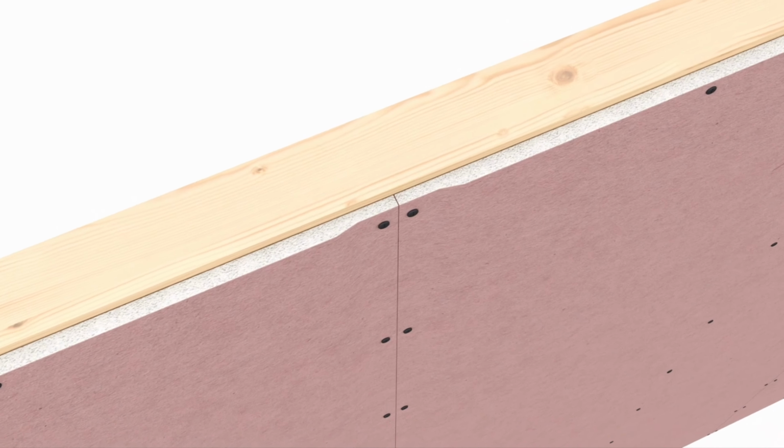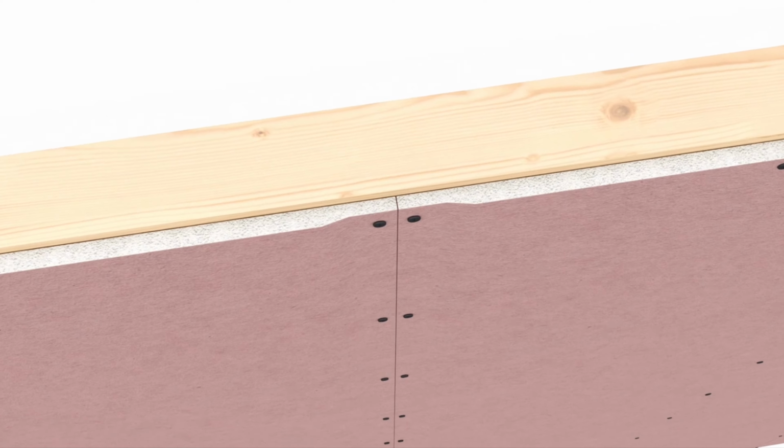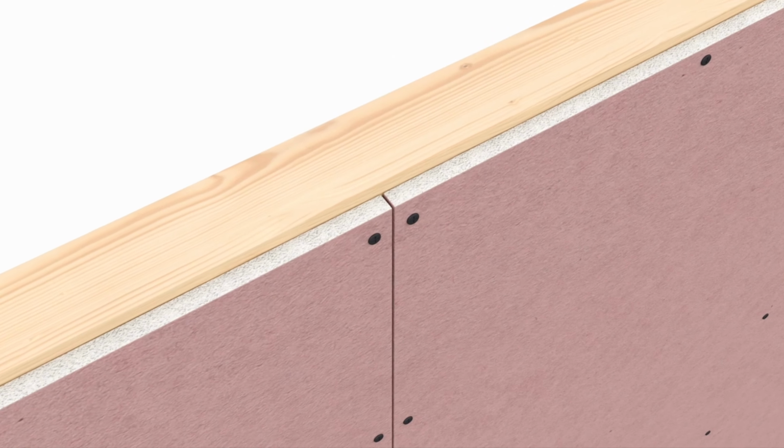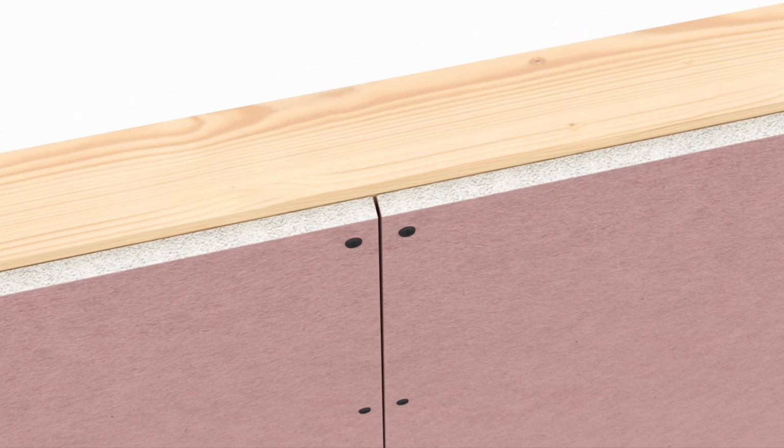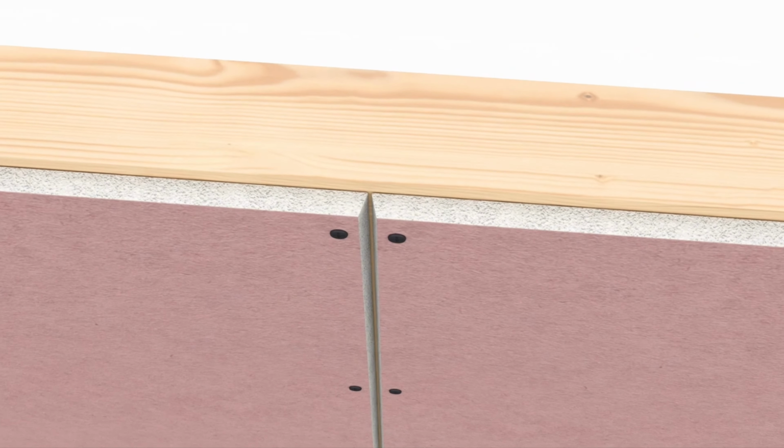Plasterboard sheets are produced with a thinned edge at the long side. If a cut edge remains at the joints of 2 adjacent plasterboards, then in order for them to be puttied and finished later, the cut edges must be cut obliquely at an angle. Such a requirement applies to all layers of plasterboard facing the room, regardless of the number of layers of boards